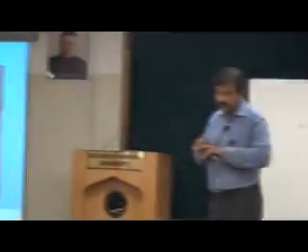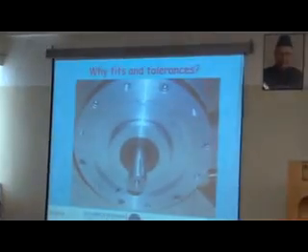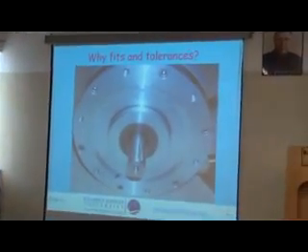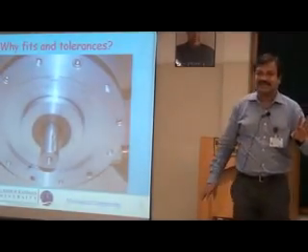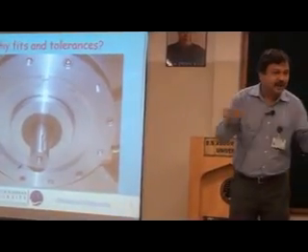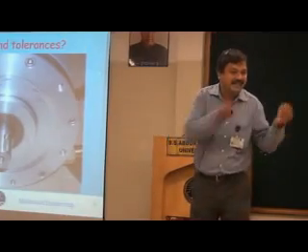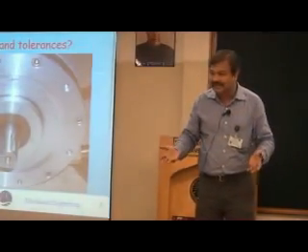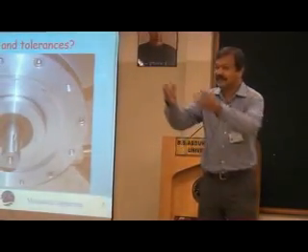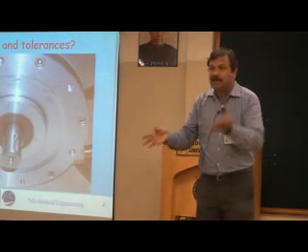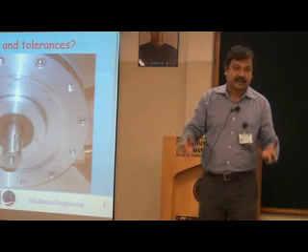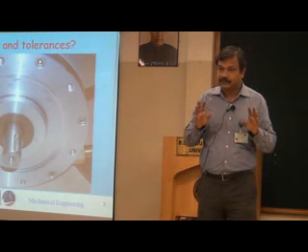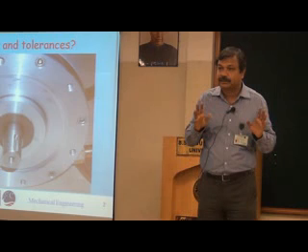Now let's take the question, why fits and tolerances? The reasons are twofold. Why should I give a tolerance? Because the exact dimension doesn't exist. It is not possible to manufacture to an exact dimension, and it is not possible to check an exact dimension.